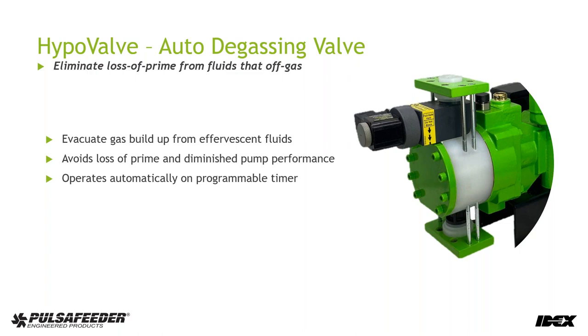So this means that for you, the customer, it's possible that once air builds up on that process side, your pump is literally working inefficiently, using electrical power and not delivering any chemical. Or it's got to operate faster because it's not pumping efficiently. And so that means higher costs. That means more electrical usage, and we know how sensitive and important it is these days to be energy conscious.